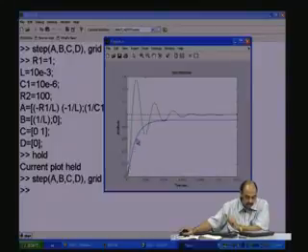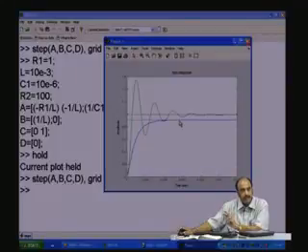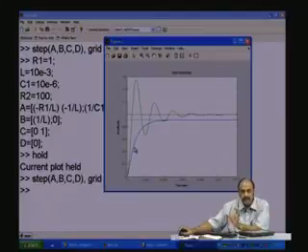Here, you will see the poles. Now, here there are 2 energy storage elements, therefore, there are 2 state variables, and therefore, it is a second order system, therefore, there will be 2 poles. So, the number of energy storage elements is going to directly influence the number of poles. If there are n energy storage elements, there will be n poles. In the earlier situation, both the poles should be somewhere close to the real axis or on the real axis.